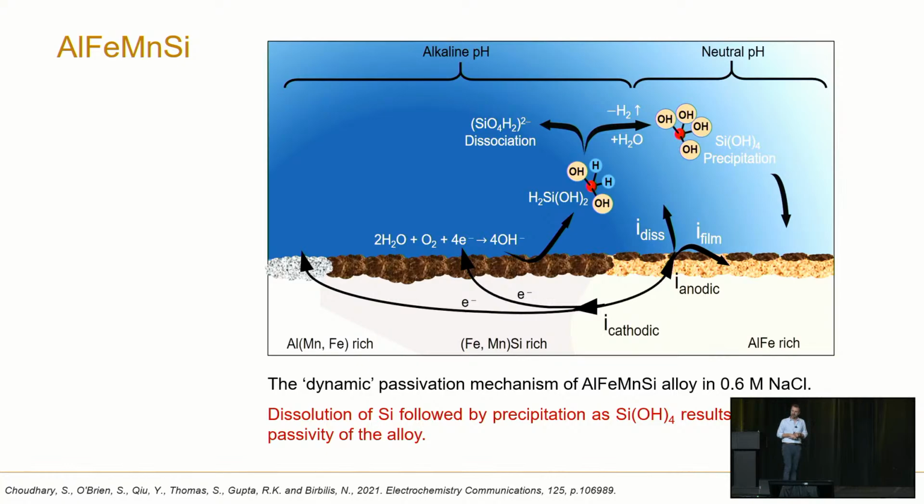So this particular alloy is like the one I showed earlier, the aluminium, titanium, chromium, vanadium. But actually what happens is after some early immersion, which you can only really understand by doing this atomic emission spectroelectrochemistry, you do get an enrichment of silicon. That silicon can also then redeposit and form a silicon hydroxide, which then becomes super, super stable. It creates compounds that are very much like the rocks that you find in nature. So really interesting that this alloy can be made.